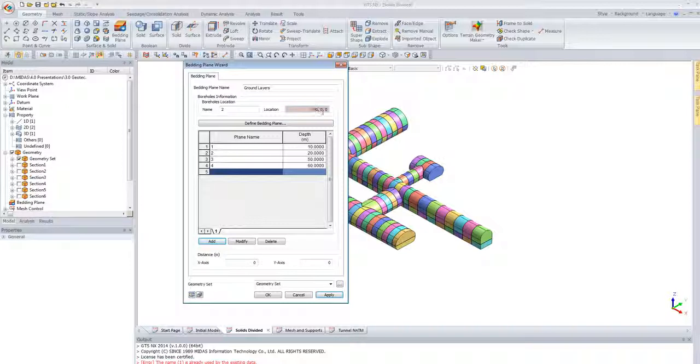As you can see, we could put a different value, a different location, a different point. So this would create the layers going across. And obviously the more layers that you create, say if we've got 4 points instead of just the 2 that I'm creating, then you will have a more detailed layer strata. So there's one more point. Just going to give you the layers.